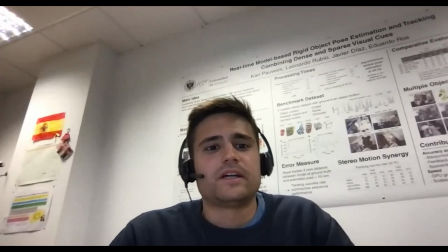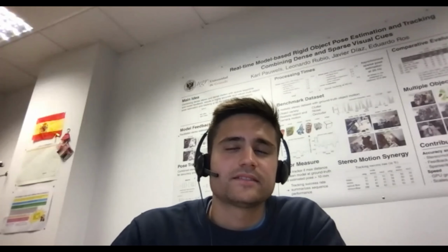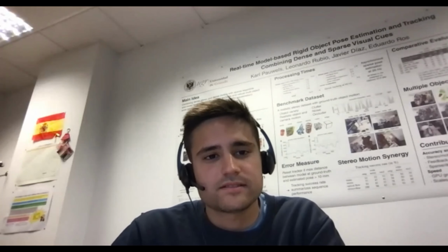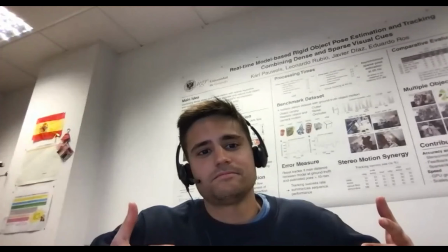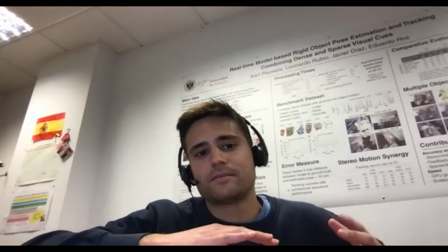Sure, why not? Okay, I work with the AXI stream interfaces. So if I want to add additional signals that aren't part of the AXI stream bus, and use them at the same time as inputs to the system, how can I manage to take them into account, to keep them constant, for example, until the frame reaches the sink?